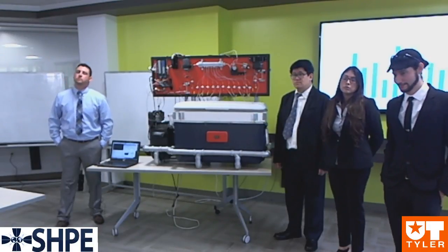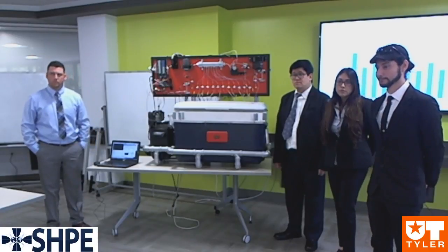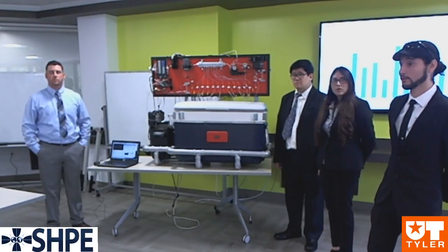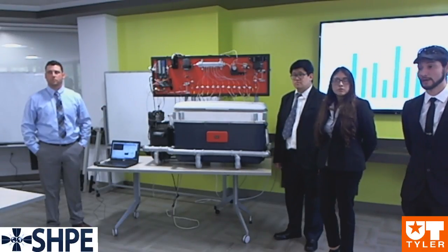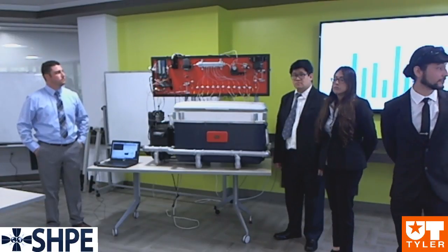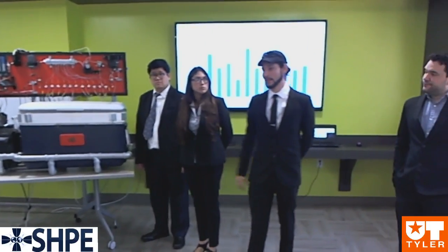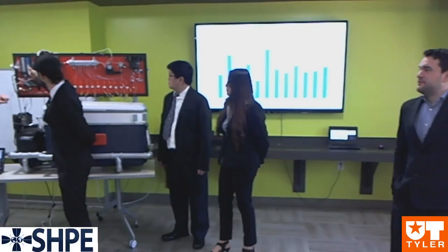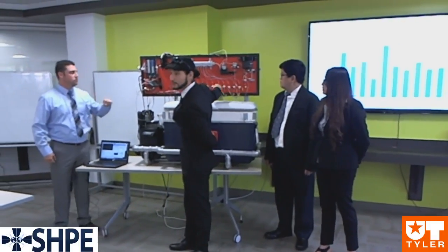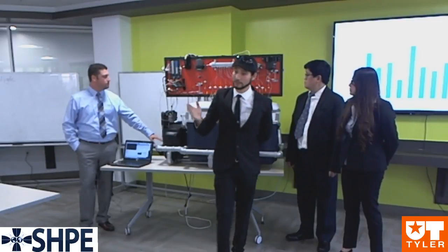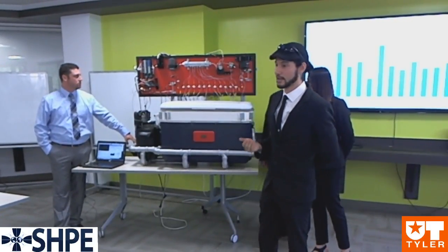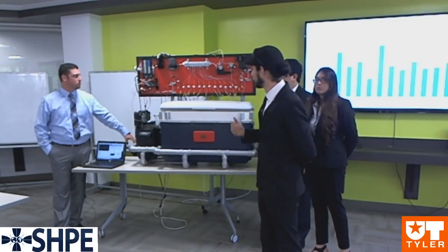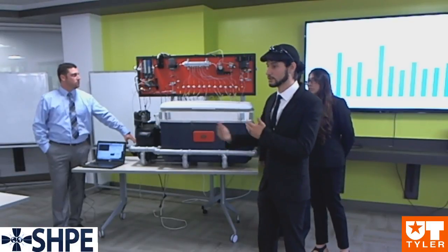I have one question regarding the software. You said it was programmed with Python? Yes, Python is used to display the data. Mostly it runs with Arduino and a side program called Processing, which is based on Arduino as well. And as Daniel explained, Arduino is the one that controls the solenoids. These are the solenoid controls right here, and each of them is connected to these solenoids. Arduino sends the signal for the cycles to open and close depending on which sample we're gathering. So we developed a program that is sequential. After it completes one, it opens the other one, and so on.